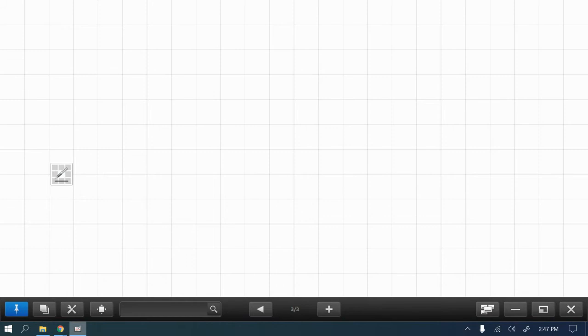This is for a general subdivision with low flow traffic, the kind where either a civil engineer or a surveyor can design the roads and the drainage. A lot of times they'll require 2 inches, depending on what you use for your base and what type of natural soil is underneath all that. But for parking and driveways, they have some suggested ones.